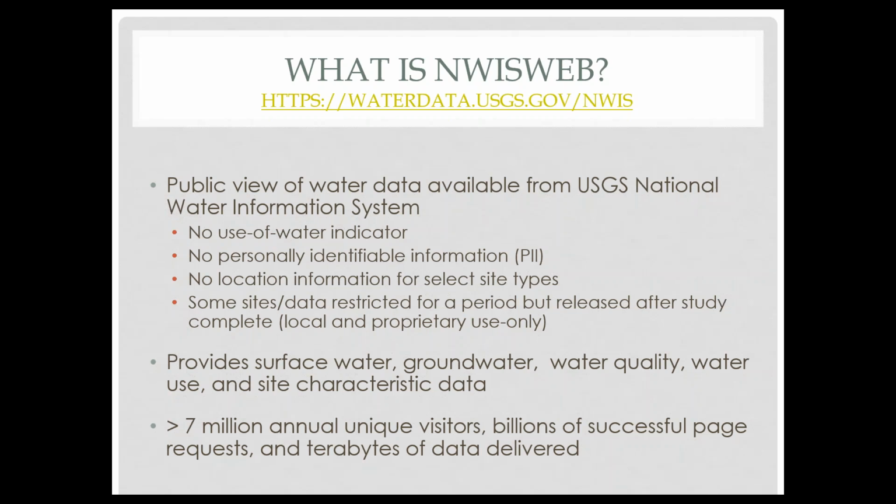One of the things that we will often do if we want to use an existing well, because it's expensive to drill wells in an area to do your study, is take a borehole camera and go down that well. If we don't have a well log, if we can't find the folks who constructed the well, we need to make sure that the well is open to the right part of the aquifer and is constructed well.